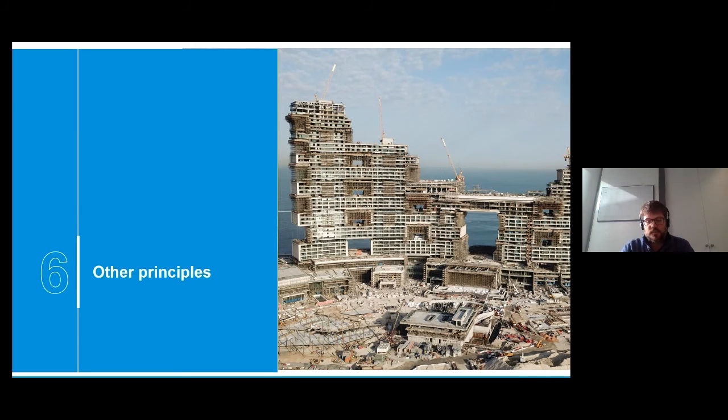And for us it helps a lot, because the concrete starts at 32 degrees at the beginning. I will just show you now how we do that. And the concrete temperature goes up during the pumping, because of the friction of the concrete in the pipes. The temperature will go higher. So actually, it's a little bit better for us that at the top of the tower it is a little bit cooler than at the bottom. But I take the advantage of this question to go on something else. Again in Dubai, because it was a really good example.